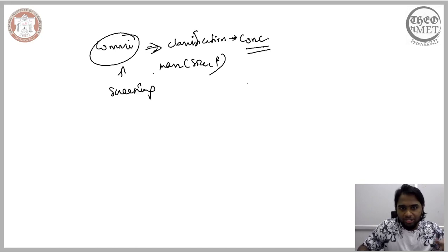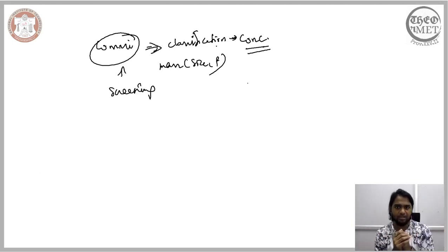So when you compare these two, screening and classification, to concentration, even though a specific form of concentration might share some traits with screening and classification, when you look at the fundamental reason why these processes are being pursued, why one has to expose the mixture of particles to screening, classification and concentration, concentration has its unique goal. The concentration intends to separate the mineral particles that we desire from the gangue particles.